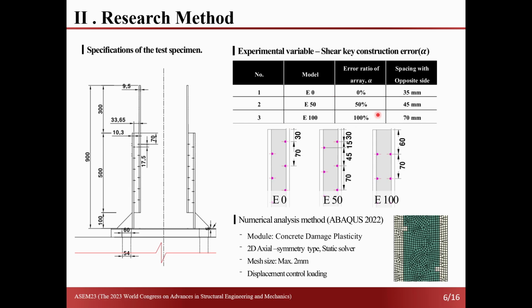For the numerical analysis, we utilized the Abaqus software and employed the concrete damage plasticity model. The mesh size was set at 2 mm, and to ensure computational efficiency, a 2D axisymmetric type mesh was used.